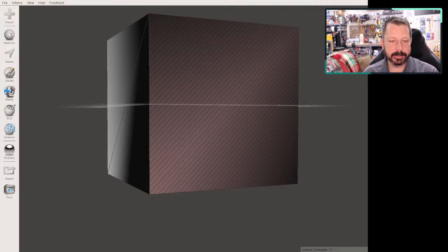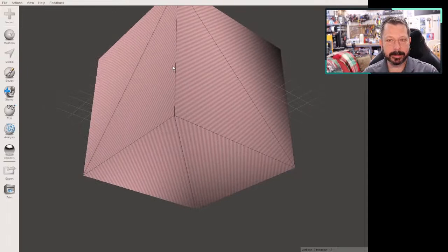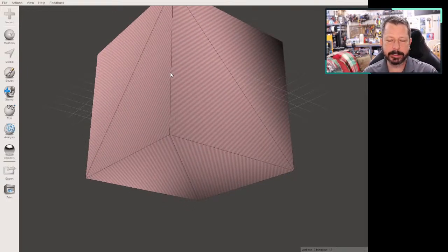So what that means is when this code was written, see this facet normal? That means the normal vector, the perpendicular vector to that face. In this case, it's actually pointing inwards, which it shouldn't be doing. It should be pointing outwards so you can actually see it. So this one technically is going to probably create problems in Cura, although Cura is generally good about figuring out what you meant.